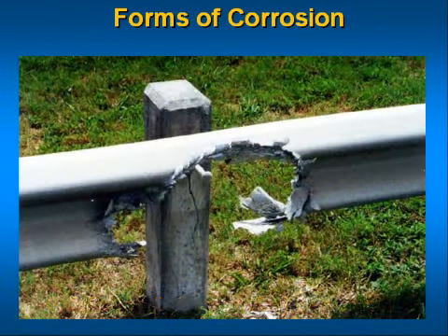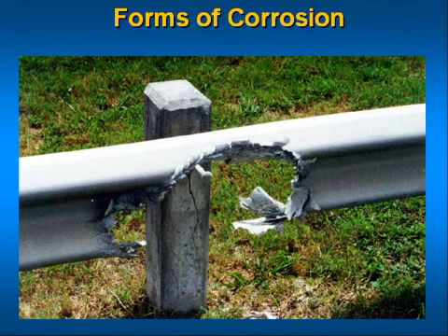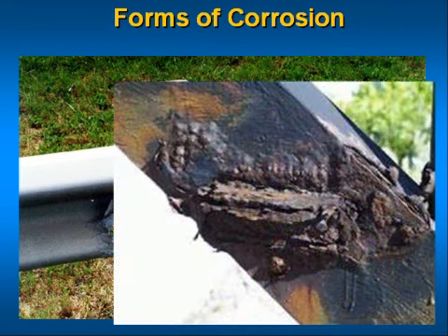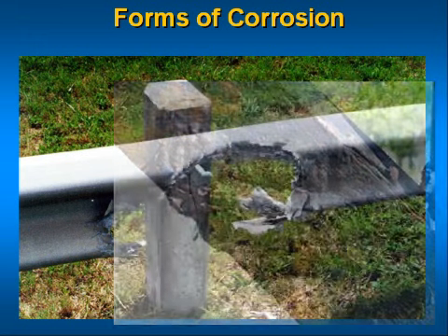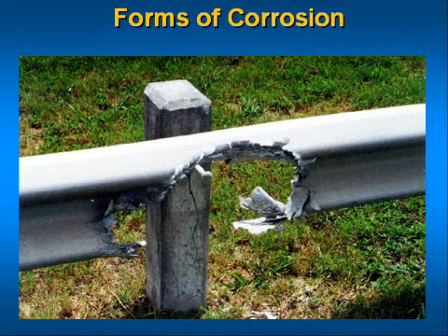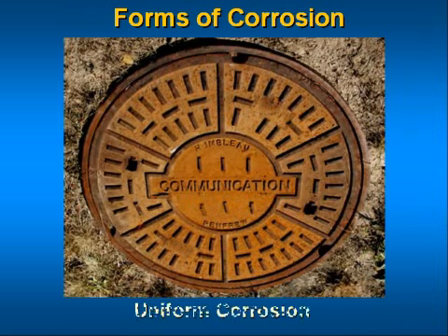Exfoliation of carbon steel is apparent in the channel on the coating exposure panel on the right. The expansion of the metal caused by exfoliation corrosion can create stresses that bend or break connections and lead to structural failure. Uniform, or sometimes called general corrosion. The surface effect produced by the most direct chemical attacks is a uniform etching of the metal. The facilities shown in the picture at the right show how this corrosion can progress if control measures are not taken.